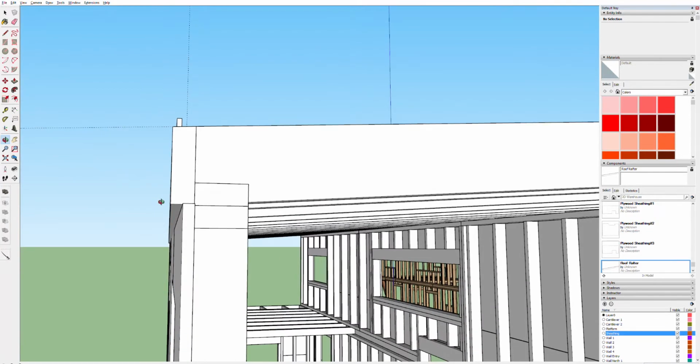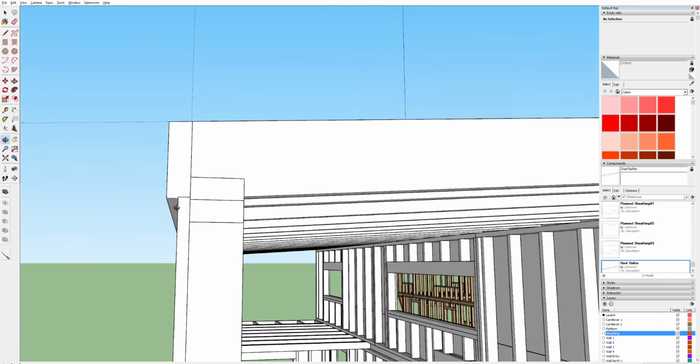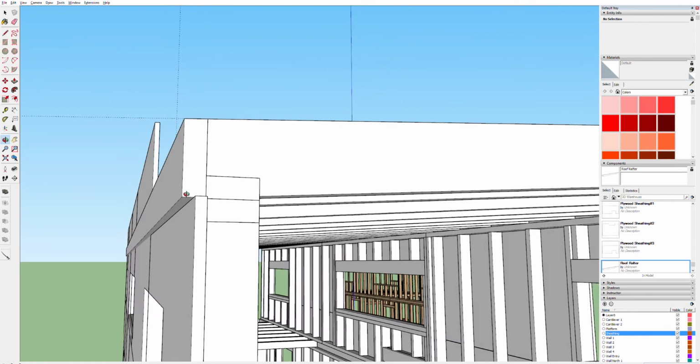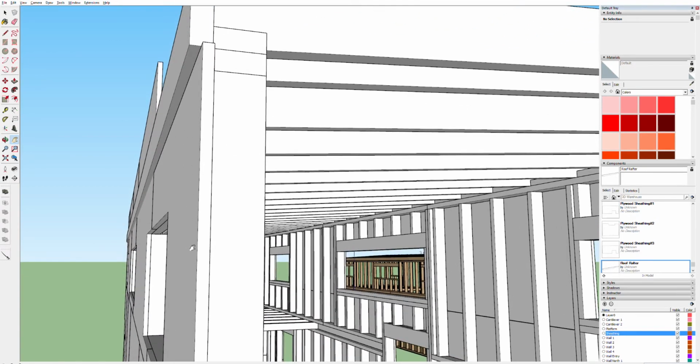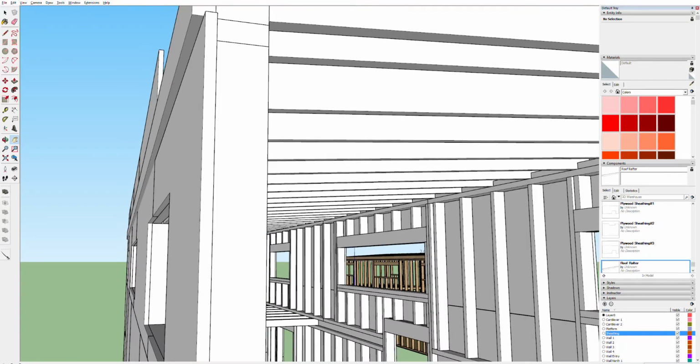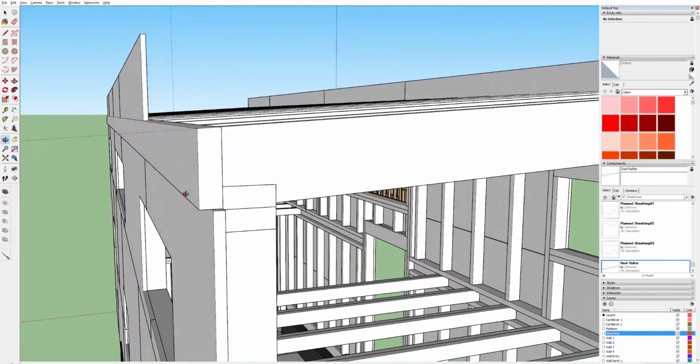flare it a little bit. Actually, no, we're not going to be pushed out that much because we're going to end up putting our siding on here next. But hopefully with that little bit of a flare, it lets the water drip away from the house a little bit. A lot of it will probably eventually hit the siding of the house and then drip down to the ground that way. But the idea is to get the water to drip away and at least hit the outside of the house, not somehow make its way into the sheathing behind all this stuff. But that'll make more sense as we get into it.